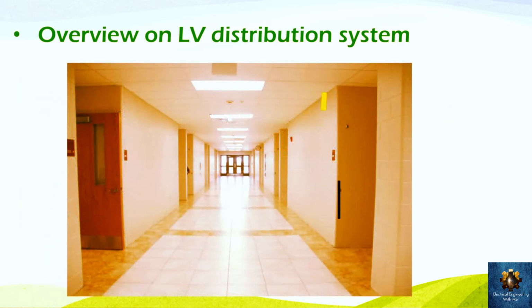Also, we can represent this system in some detail. Suppose we have this sub-main distribution panel inserted at that position of the corridor. Here we can go out of it with some wires that are inserted in some conduits, and those conduits lie inside the wall, not outside it or on the surface of the wall, but embedded inside the wall.